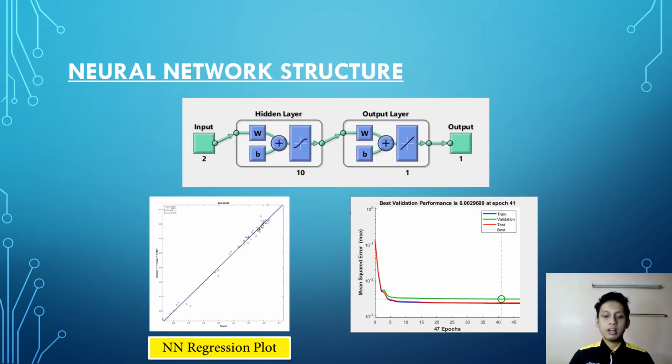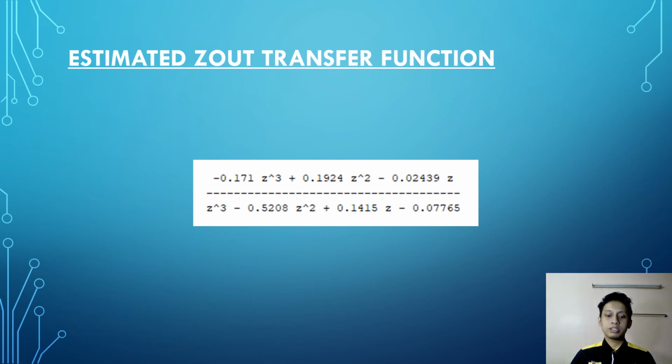The model values are then used in MATLAB's neural network. Hundreds of data are viewed by artificial intelligence and trained repeatedly to have the same system model as the transfer function model from system identification. Regression plots are obtained for validity of the system model generated. After verifying the accuracy of the system model, the output impedance, or ZOut, model transfer function is then used for pass-fail tests of unknown points that have not been analyzed from manual testing.